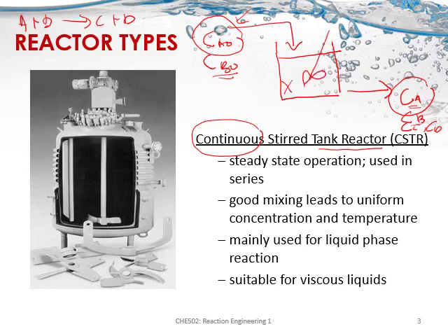Again, we have an impeller or a stirrer in a CSTR. The description: steady state operation, used in series. What is steady state? You learned in fluid mechanics that steady state means the conditions do not change with time. The condition here refers to the concentration, the most important parameter, temperature or pressure.